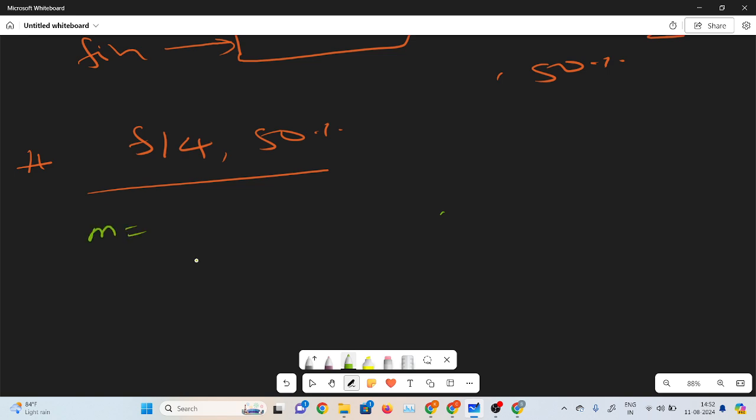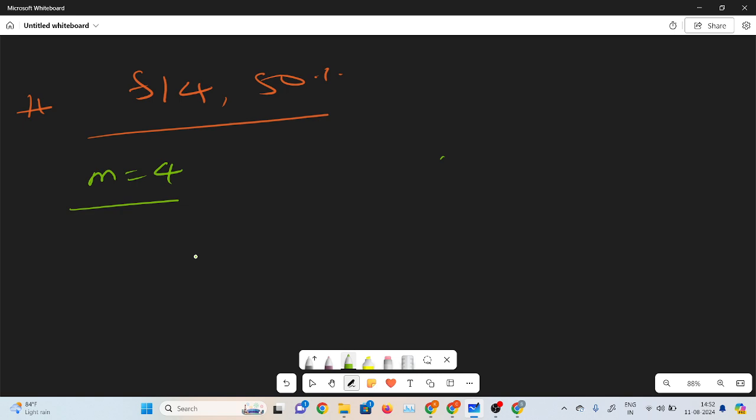So what is the mod value? That is 4. So here I use the mod 4 counter, and there are a total of 4 states. I am naming Q1 and Q0, where Q1 is the MSB and Q0 is the LSB. By default I will use the up counter, so the count is 00, 01, 10, and 11, that is 0, 1, 2, and 3.